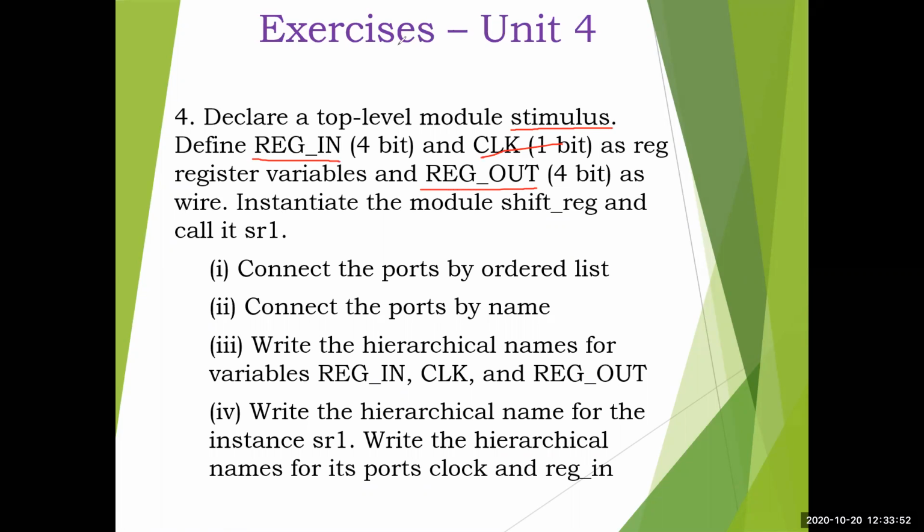This is like a stimulus module, so you need to call that design we have written previously, by the name sr1. Then in that module, connect the ports by ordered list. When you are calling this shift register, first case you call by ordered list, second case you call by name, connecting ports by name. Both you have learned, so you have to do it simply.